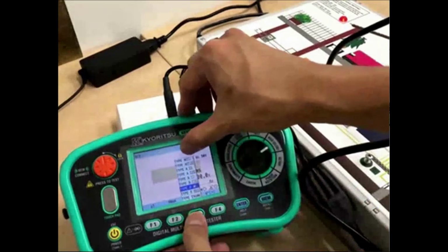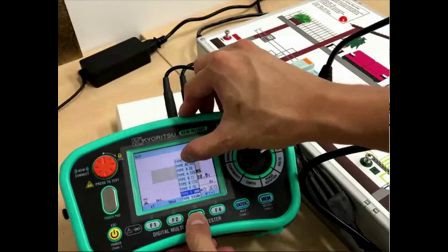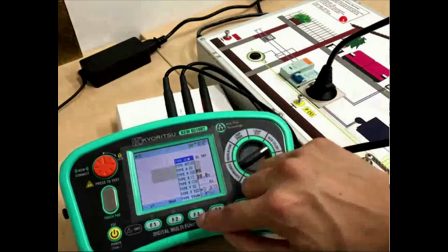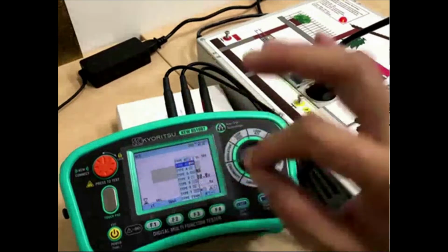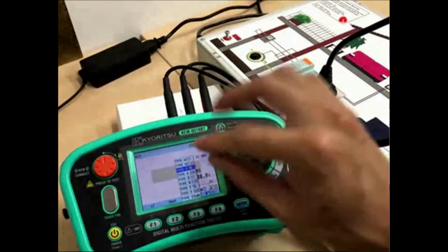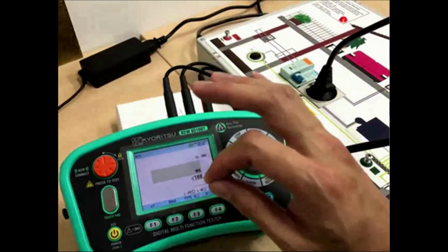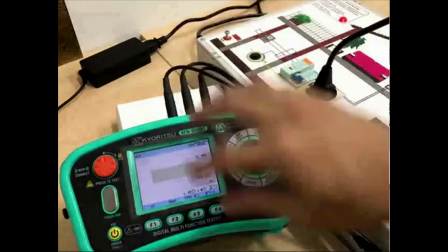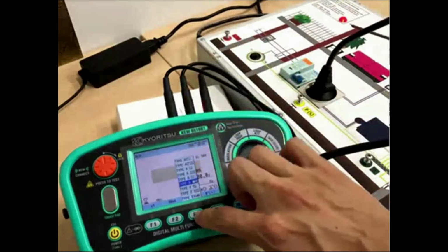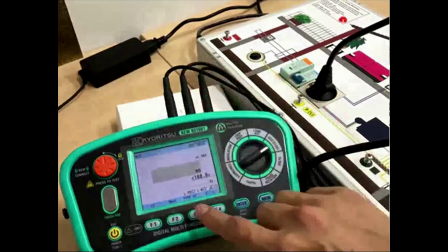You see here, RCD AC general, RCD AC selective, RCD A general, RCD A selective. What is this selective and what is the general? General is without tripping time delay. With selective type is with tripping time delay. Some circuit design, they need this tripping time delay. I don't know why. You'll go and check out why they need this tripping time delay. But in our case, we don't. Our RCD is AC type and general type. Okay, we set it to this type.